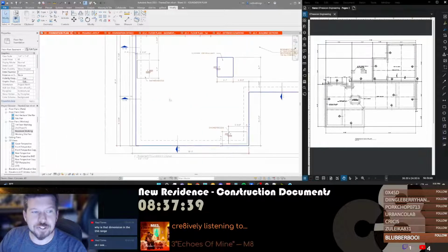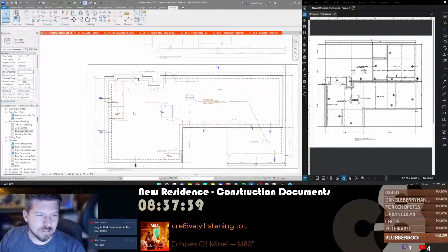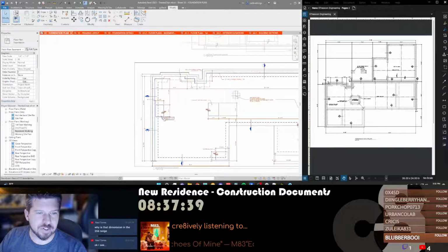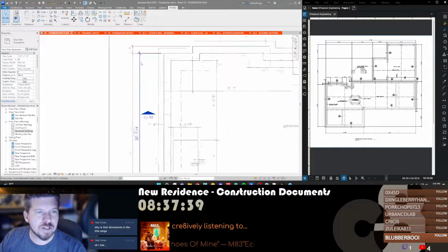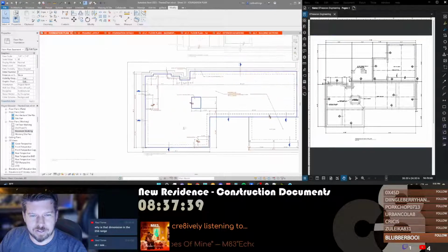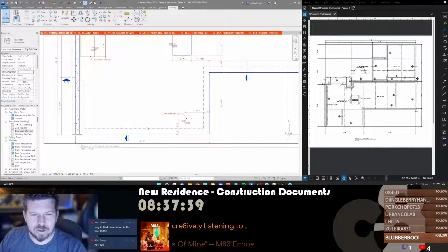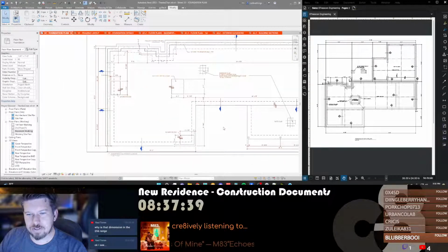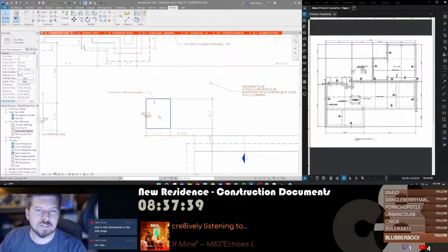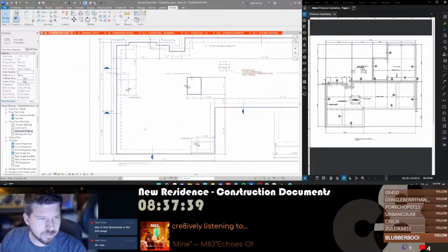So that is intentional. Because it drives me nuts when I am trying to document something and overall dimension is 1/8 of an inch off or a quarter of an inch off because of rounding errors. Because someone decided, hey, you know what? I can just use my arrow keys and nudge this around and get it close enough. When really all you have to do is select an object, select the dimension, type the exact number, and it moves exactly where you want it to go. Too many lazy people in my models. That's what that's a product of.